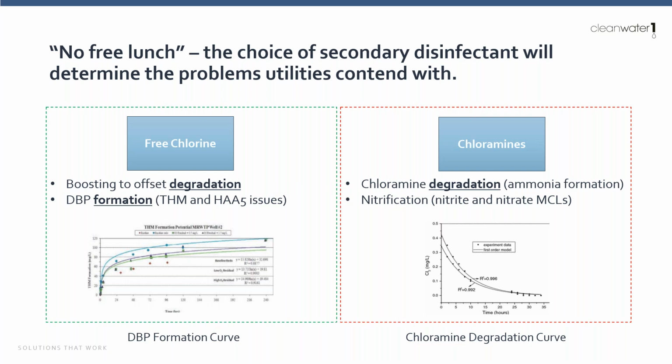And so, yeah, chloramines, got a whole host of technology to deal with some of the issues that come with those. Free chlorine is really what we're focusing on today, and free chlorine is still the most common form of disinfection. With free chlorine, you've got a less selective oxidant, and you've got lots of oxidation of natural organic matter or total organic carbon that happens as part of the process. And so you end up forming a lot of disinfection byproducts. There are two regulated DBPs, trihalomethanes and haloacetic acids, and we'll talk more about both of those in just a minute.